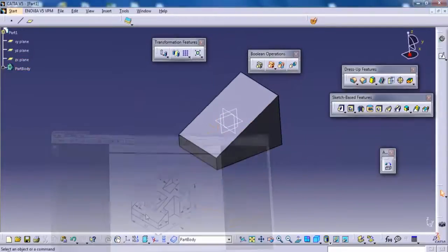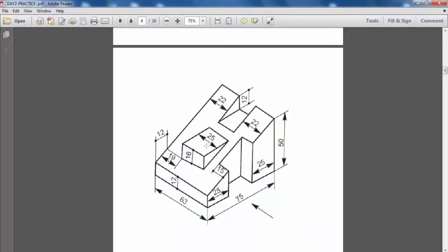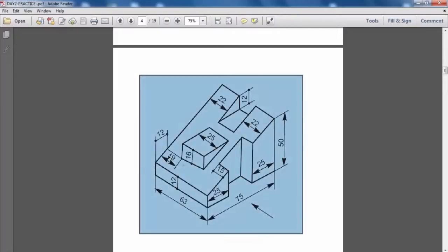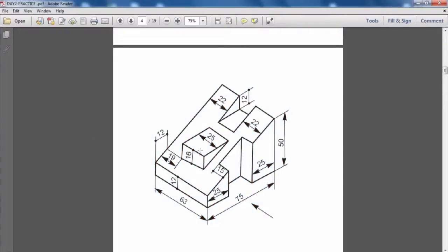Now what we can do here, we can create this one also. So for creating this entity, you need to create a distance of 12 millimeter in the slanted mode, and after that this shows you that it is 19 millimeter from left. If it is 19 millimeter from right, then what will be the length? 25. No? So 25 plus 19, the length will be 44, right? So 44 and 63 minus 44, how much the size will be? 19. That means that is totally symmetric job. The job will be created at the center point, right?